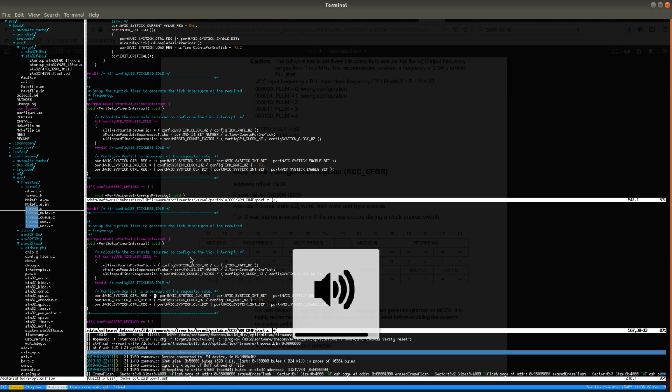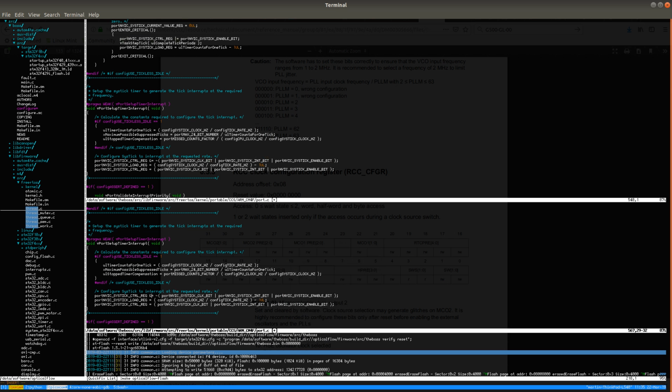Nope. So reset the bits, then update the reload register, and this will be... so I'm thinking this may actually be 100 megahertz, while the system is actually running at 50 megahertz. Could that be the problem?